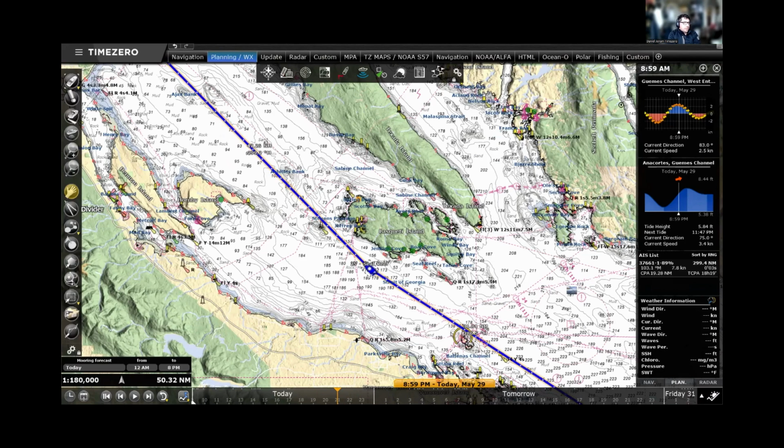A lot of times chart plotters are really hesitant to take in external route information from a source that isn't theirs. I know that's definitely the case with Furuno. I know that's definitely the case with Garmin. On some of the Raymarine screens, the route synchronization, you'll see the route on the chart plotter. On the other systems, you'll see it on your autopilot, or if you have a little 4-inch deck display, like a GMI 20 or one of the little Zeus displays, you would see it there.